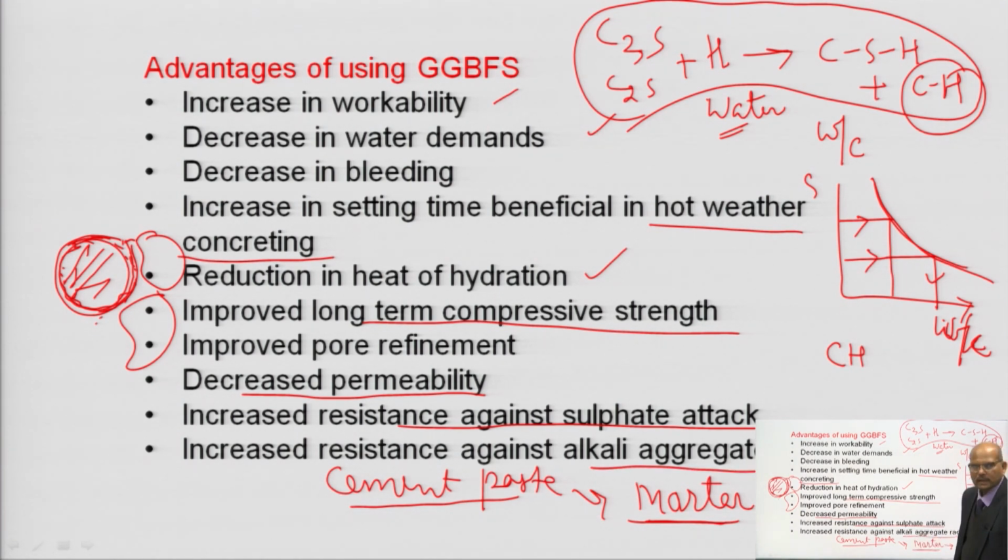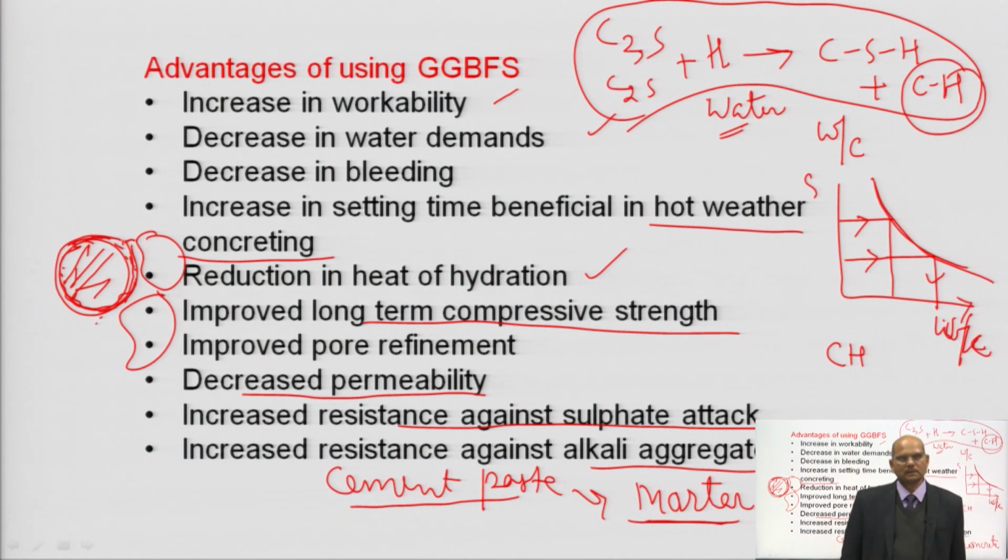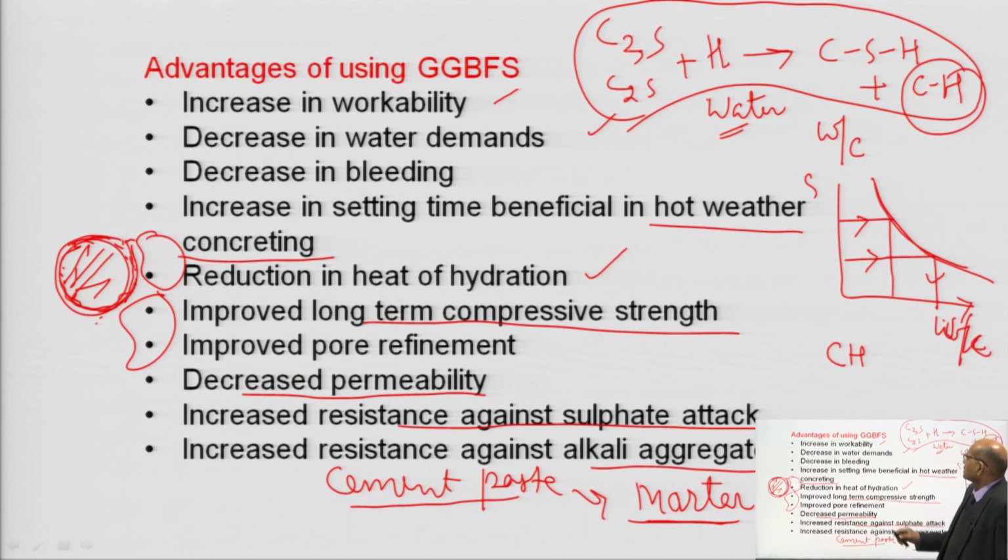If your aggregate has reactive silica present in it, in that case if you are using GGBFS, that reaction will be very slow. So, this is the advantage of using the GGBFS. But another disadvantage is also here.